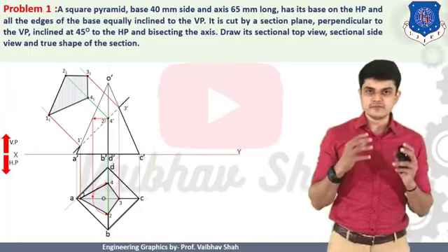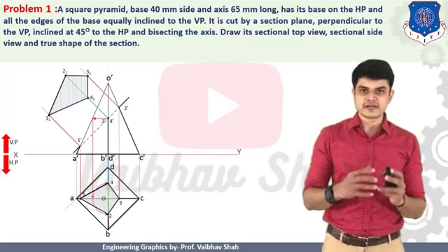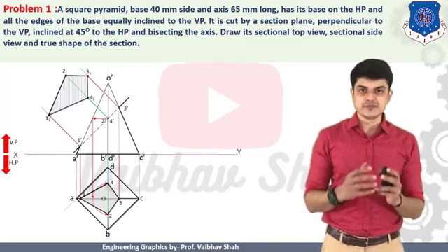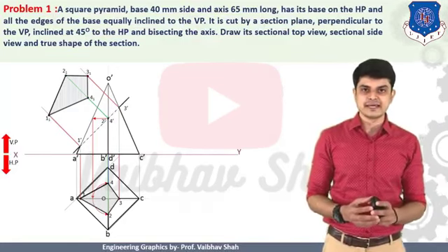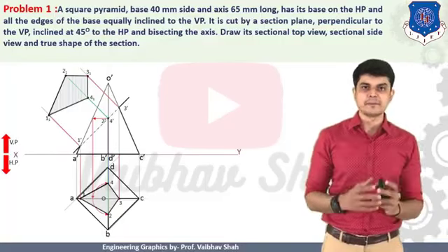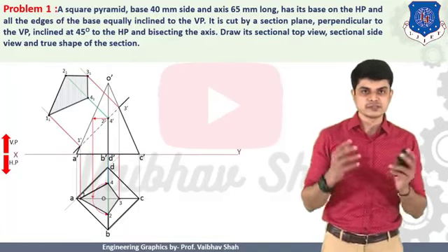So now we should move to our next and final point. So here it is said to find out the sectional side view. So what we should do? Firstly we should construct an x1 y1 line, and onto the right hand side of your front view we'll be having our profile plane, and onto that plane we should try to generate our sectional side view.